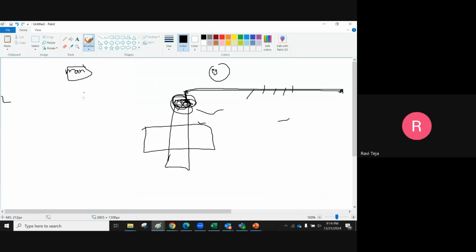That's what antenna violation is. That means this gate will act like an antenna, which will try to pull all the charge accumulated on this metal, and then the gate oxide will be damaged. That's what the antenna violation is.